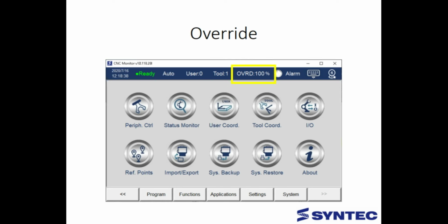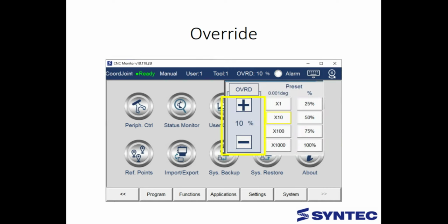The override mode basically controls the speed of the movement and motion of the robot arm. At manual mode, the interface is displayed so. The range of the override offered is between 10% and 100%, with the latter meaning the robot arm is moving with the highest assigned speed. Alternatively, the user may choose the preset incremental value and override percentage available. During auto mode, the button of the incremental movement or InJog will be deactivated.